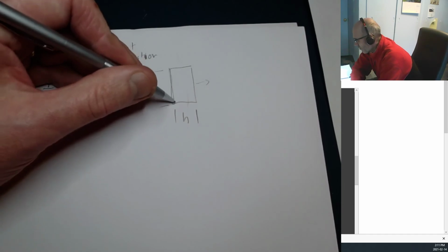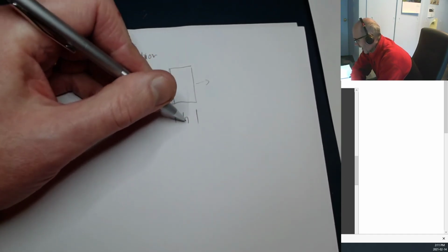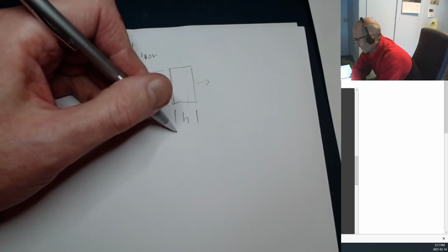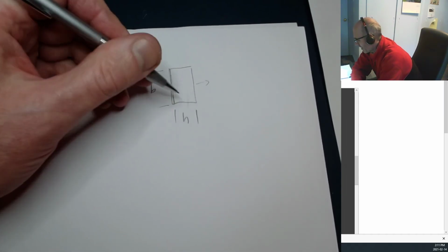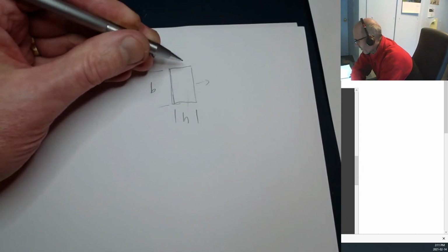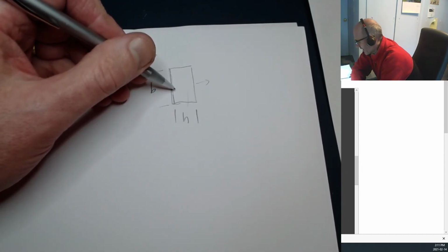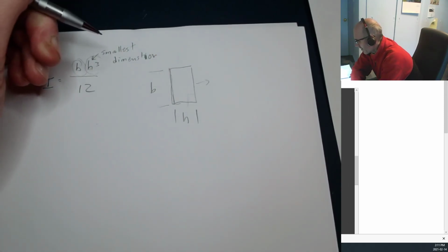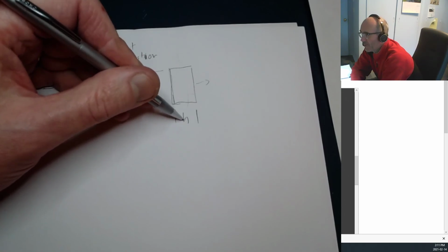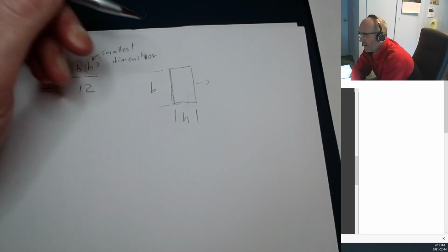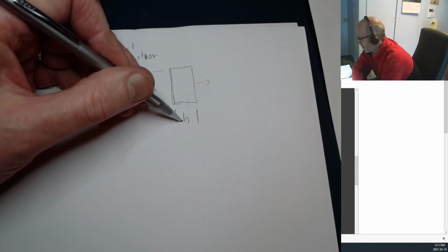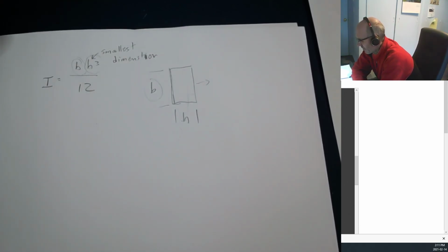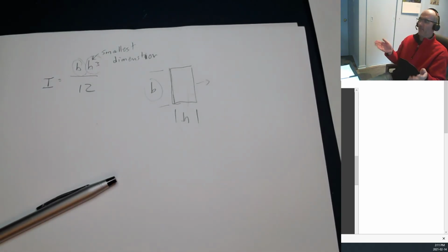Now, we're pretty much limited here. For a lot of these members, we're going to have H being 3 millimeters because we can't make it any bigger than 3 millimeters thick. If you've got some very lightweight members in there, you might get some where you can actually cut them down so that they're less than 3 millimeters. In that case, you have control over H. But as soon as you get above 3 millimeters, the thickness of the wood says your smallest dimension is going to be 3 millimeters, and the only thing you can do is make it thicker. Or wider, I should say.